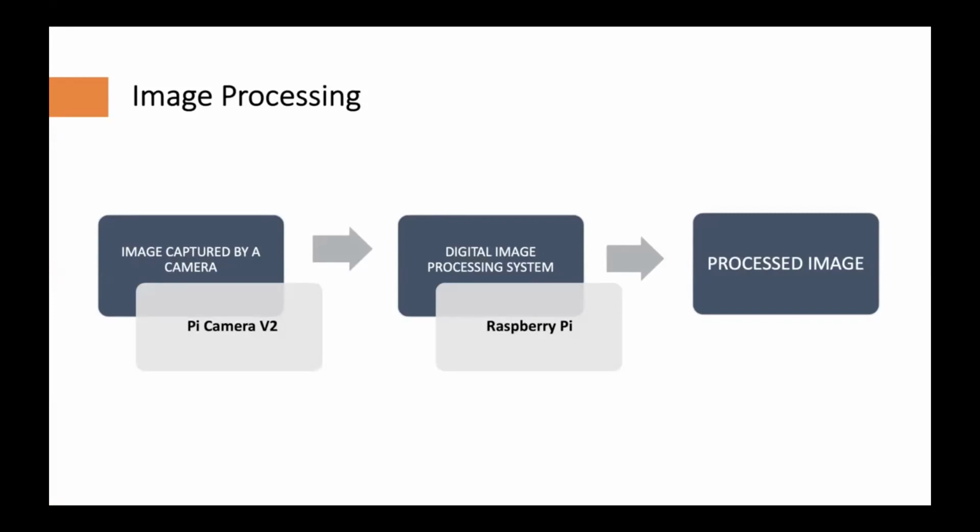Also, we'll need a module to process the image, so we'll be using a Raspberry Pi 4 board that is the central module of the whole embedded image capturing and processing system. As shown in the figure, its main parts include main processing chip unit, memory, power supply, HDMI, the Ethernet port and the USB port. Regarding the connectivity of the Pi camera and the Raspberry Pi, the way we'll be connecting both of them will be through the small socket on the board using the dedicated CSI interface.